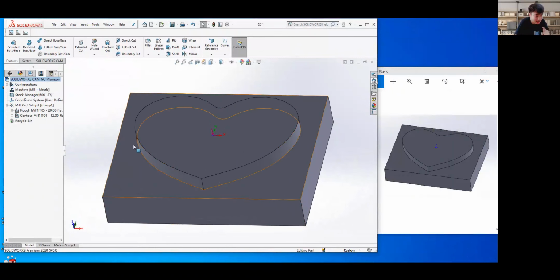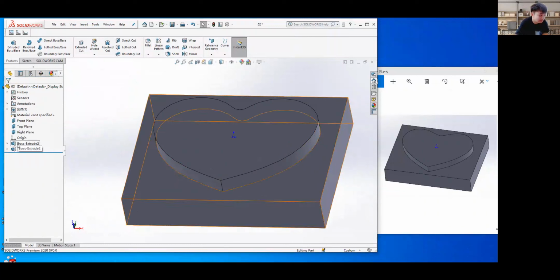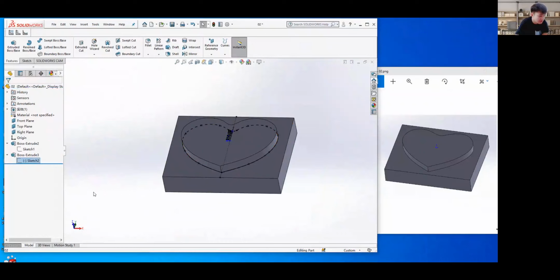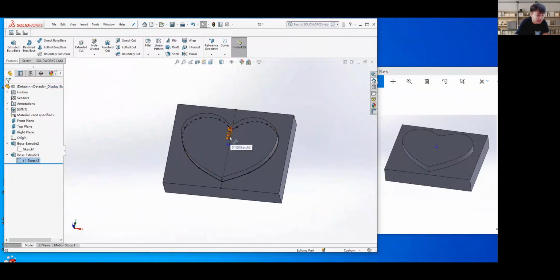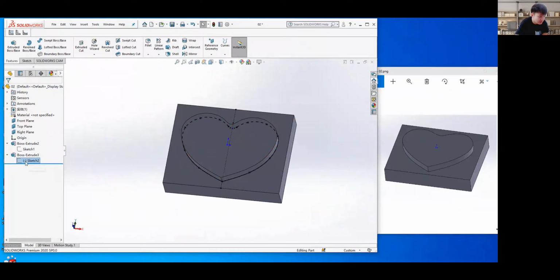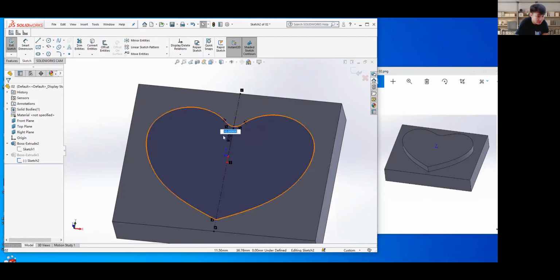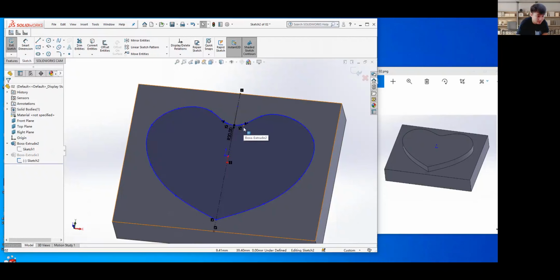And what I just told you about: if you want to make some changes to a dimension in the part design, you don't need to do it all again, right? You can just change it in the part design. Just click the triangle button here and find the part design here. See that? So how about now? I want to change the fillet dimension. Okay, let me see. Add the second sketch, the second sketch of the heart shape right here. And you can change the dimension for the fillet to about 20.